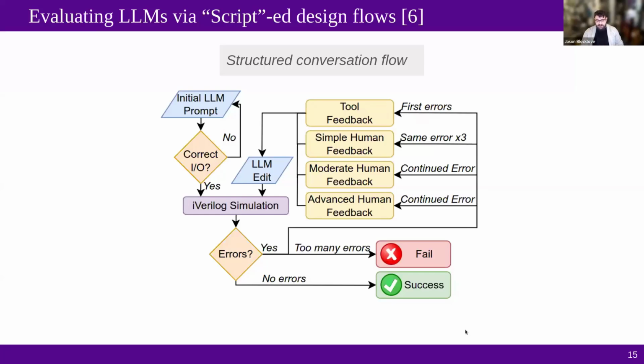It's not very well shown in the flowchart here, but the next thing we asked for was, can you make a test bench for the design that you just made? And it would generate that, and then we would throw it into Icarus Verilog, which, for those who aren't aware, is an open source Verilog compiler and simulator. Coming out of that, if we had errors, we would start feeding those back into the tool. If we didn't have errors and everything passed, we'd call it a success.